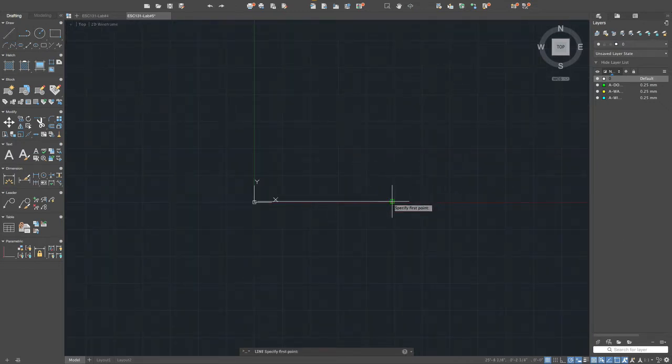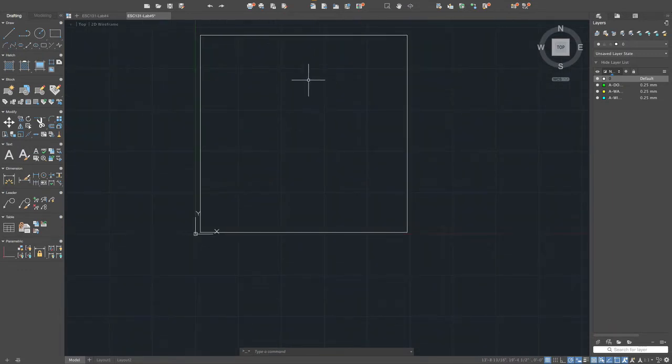Then in this direction you go 24 feet and then 10 inches. Go in this direction 25 feet and then 1 inch, and then you can snap that over there. So this is the very exterior side of the house, or the floor plan.